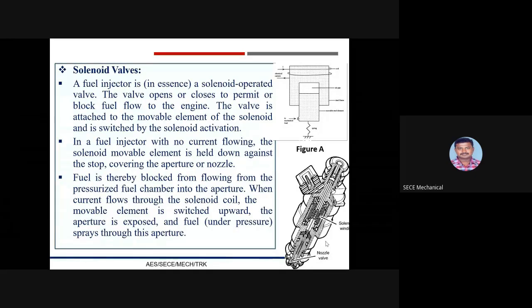The solenoid valves also convert electrical energy to mechanical energy, which causes a magnetic response. The solenoid activates when an electrical current comes through the wire coil. There are many different types of solenoid valves available, though direct acting and pilot operated valves are the two main categories. I think you may have one doubt: whether the solenoid valve is controlled by AC or DC.